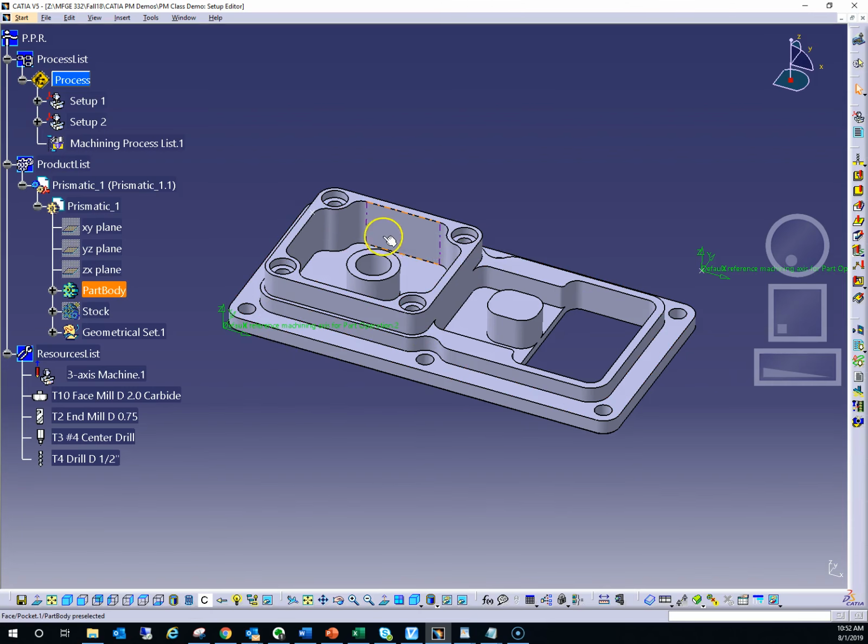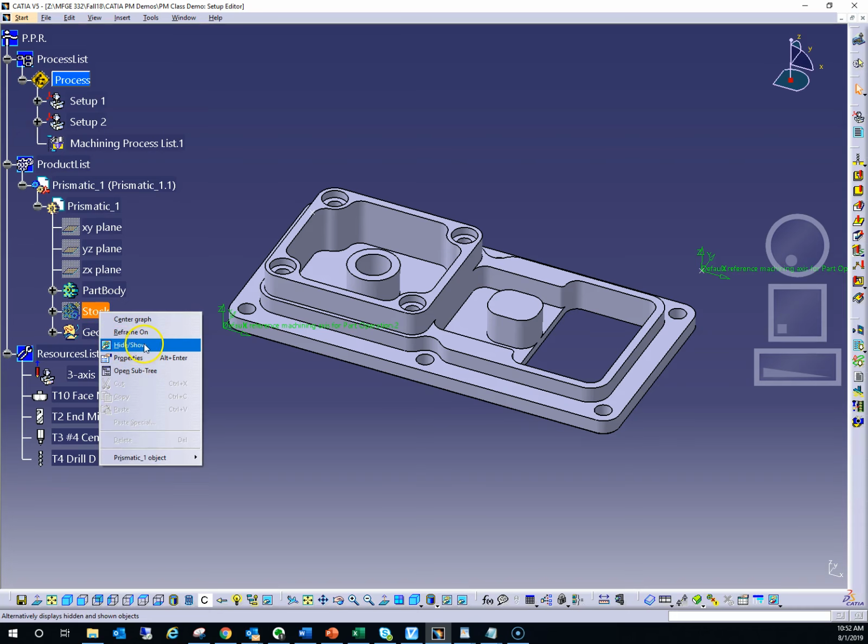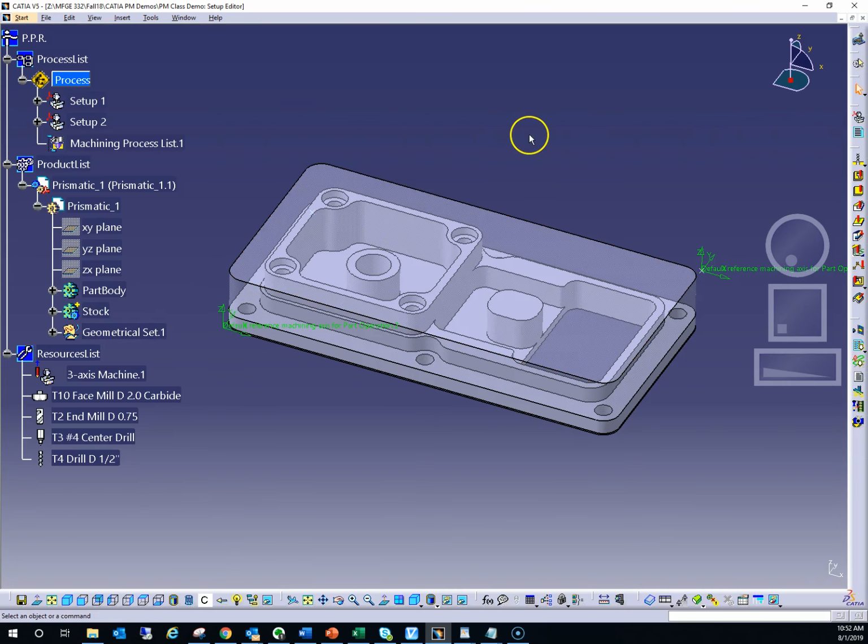And then we get into these regions here, which are generated using pocketing operations. We haven't looked at that operation yet, but that's definitely something that will be needed here. So to remove this material here, as well as to remove this material in this pocket here. So let's look at how some of the material that you are going to remove would map to different types of operations.